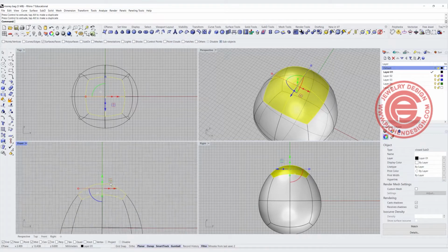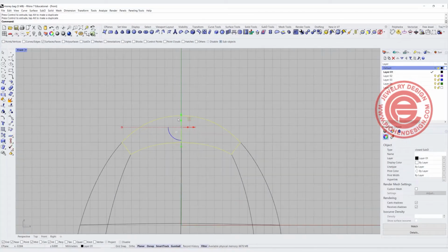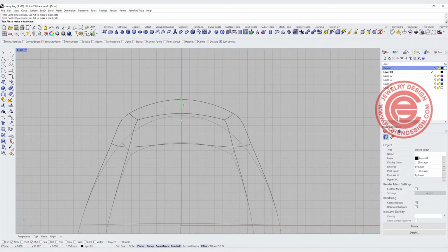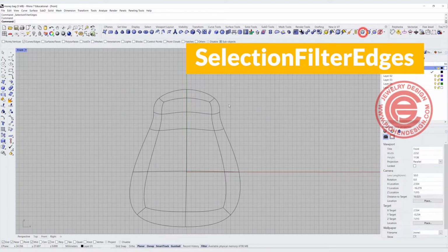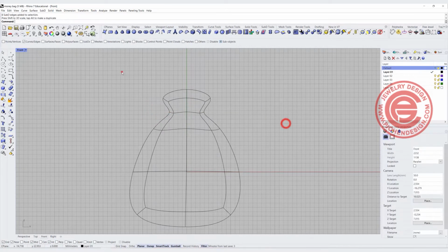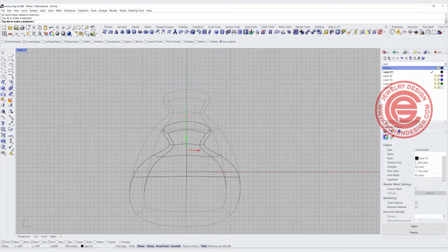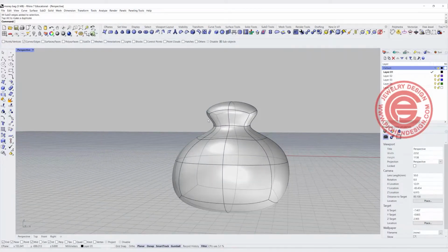So what I wanted to do instead of pulling right here on my Rhino gumball, you can see there's a dot there. So instead of pulling the faces, I'm actually extruding. I'm going to extrude it one more time right here. So now we have an extra surface that we can play with. I'm going to pick the selection for the edge on my SubD and scale it down, holding my shift key, something like this. And then I want to move everything down so it's nice and round. Now if you look at this, we have the shape that we want. It's tidied up on the top.